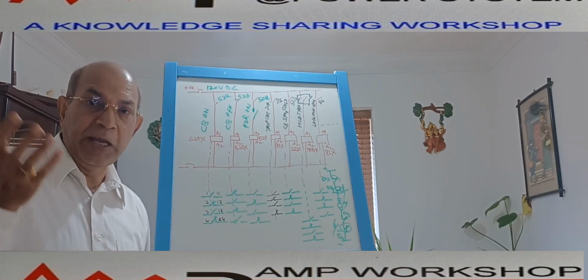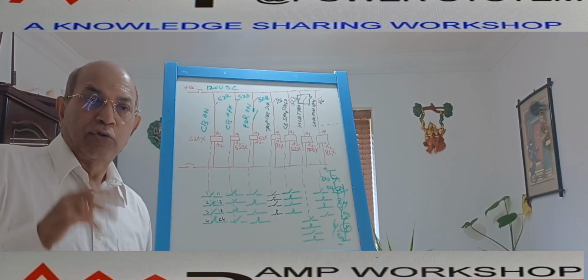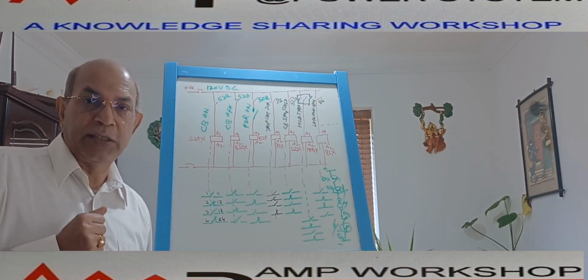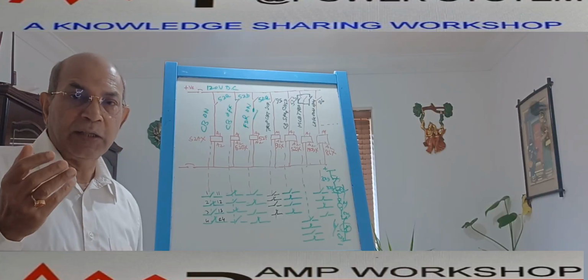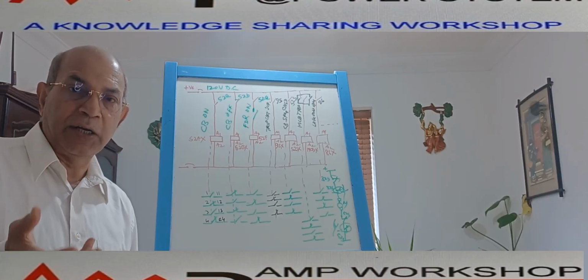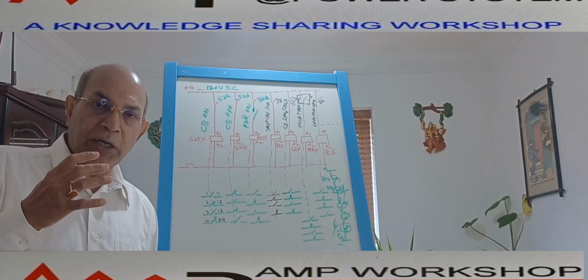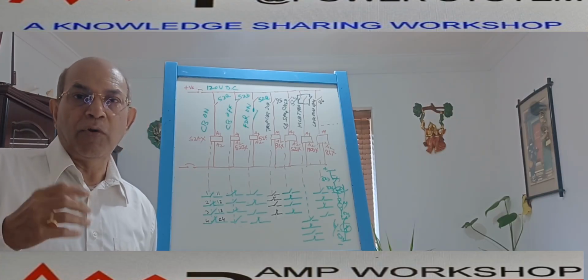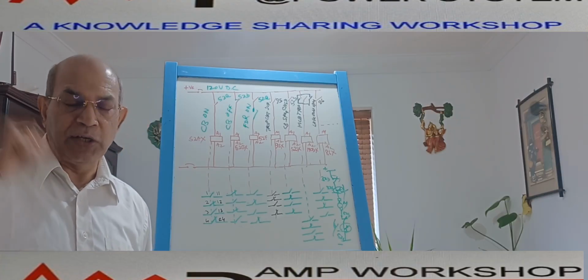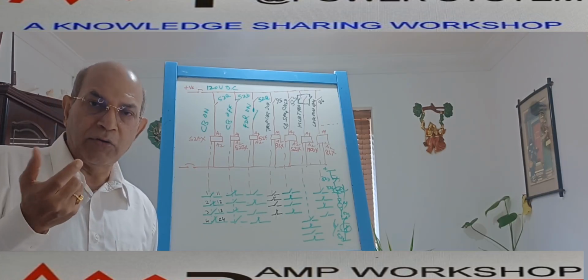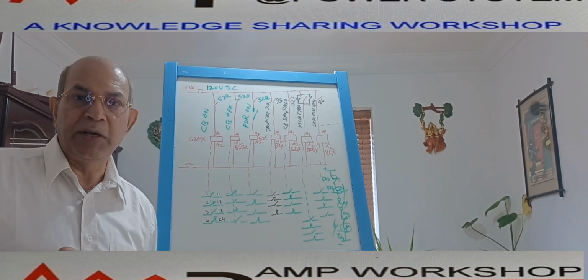Similarly, if the pressure is very high, that is also dangerous. This limit switch has only 1 NO NC contact. Now you want to monitor the SF6 circuit breaker pressure condition in the switchgear panel itself, in the control room, and in the remote DCS room. In that case, only 1 NO NC contact or 2 NO 2 NC contacts will not meet the requirement.